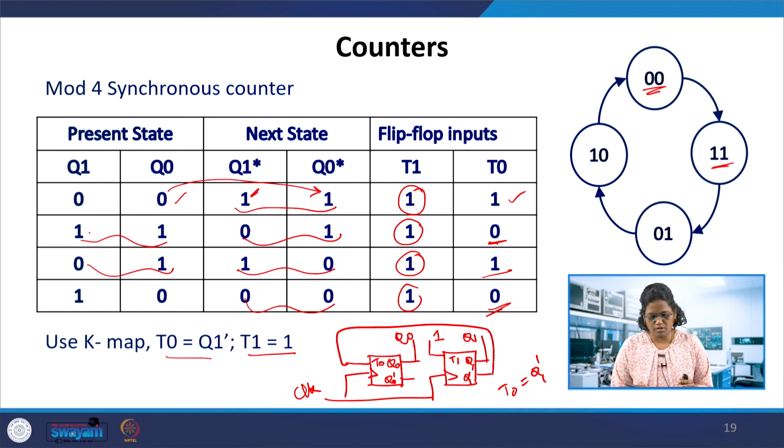There are ripple counters also, and we will see their design and how to build the smallest module. We have the D flip flop, convert it to a T flip flop, and then use the T flip flop in the bigger design like the mod 4, and then mod 4 can be extended to a further larger module. These counter designs we will see in the coming lectures.